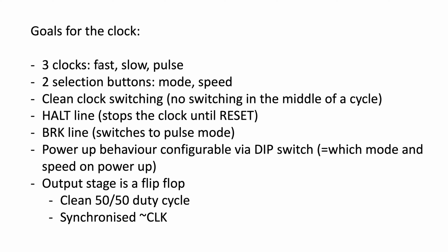And then I want the power-up behavior to be configurable via a dip switch. Which mode and which speed should it take on power-up? It depends on the situation, so it would be nice to be able to configure this. And as I mentioned earlier, the output stage is going to be a flip-flop, so that we have a 50-50 duty cycle. That's really important. And then we can get a synchronized inverted clock. So that's going to be a pretty full-featured clock.